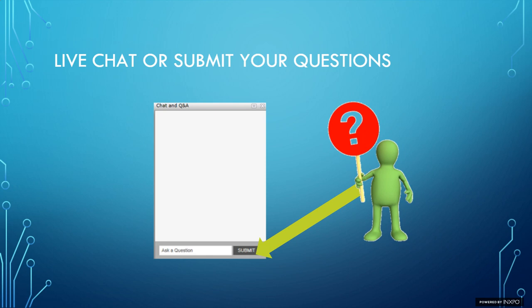So at the very end, in terms of operating costs, I think we addressed this, that an oil-free system with an oil-free compressor is a higher cost to operate than a lubricated one. But to Werner's point, which he already mentioned, it's what allows you to sleep at night the best. And then what's the specification from an end user, or if you're a major manufacturer, what's the overarching goal or stipulation from your company? Does your company say it has to be oil-free, in which case you really have no choice in that matter? It's a good question.